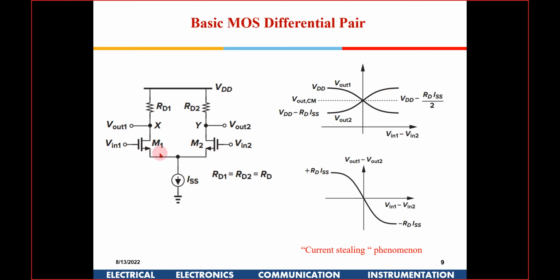Okay. If I keep increasing both the voltages together, will the operating point shift? Anybody? If I keep increasing... pardon? They both will draw equal currents, and the output will be VDD minus ISS by 2 into R.